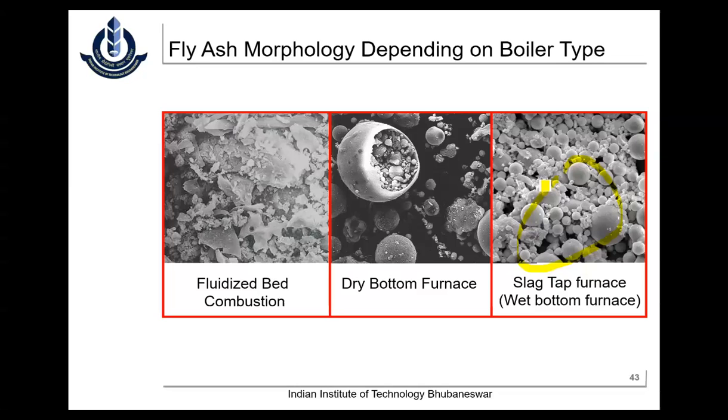If somebody asks for a high strength concrete, use metakaolin also. My suggestion is a technical suggestion I'm giving: use a small amount of fly ash. Somebody is asking for a 70-80 megapascal self-compacting concrete. We have done it. Without any hesitation, use metakaolin. This metakaolin is a wonderful product which we have proven in my lab for self-compacting concrete. This combination of metakaolin and fly ash with some other good cement, definitely we are going to get a wonderful self-compacting concrete. Please use that without any hesitation.